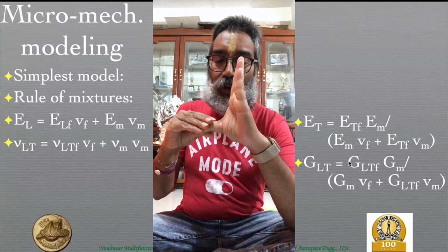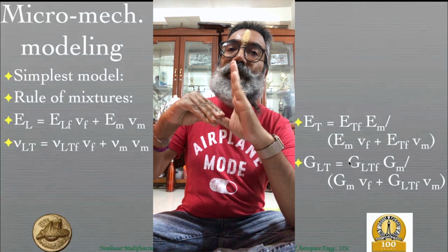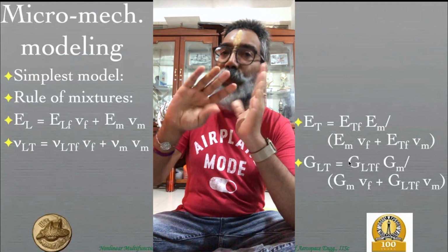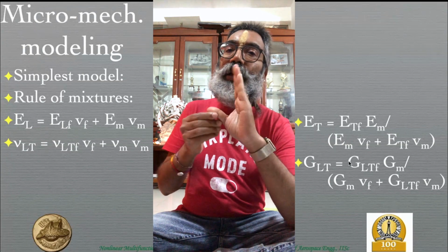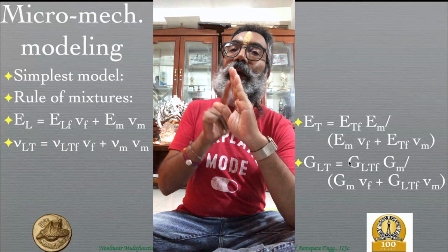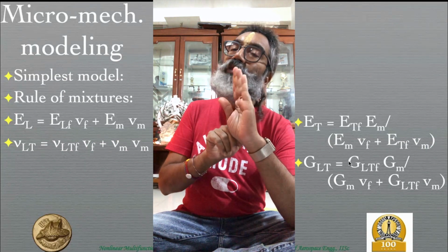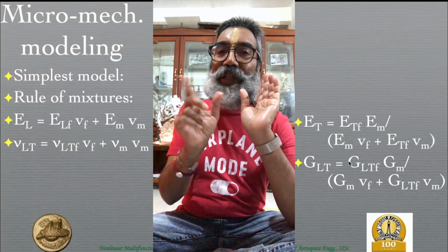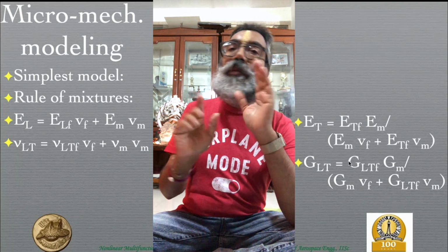So what we're talking about is a right angle changing its angle by theta, and therefore the shear strain proportional to that, depending upon whether it is engineering or tensorial shear strain, but it's directly related to that change in 90 degrees. But now what if you had an infinitesimal element which is not 90 degrees? You can always still find out the change in angle over there and relate it to this. This is just a baseline that we are having in terms of 90 degrees for convenience, but need not always be.